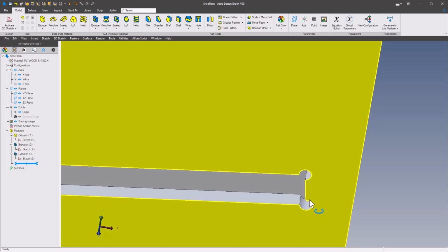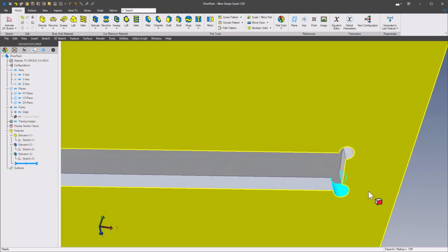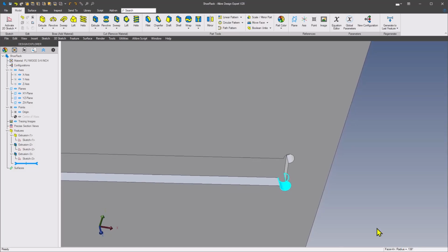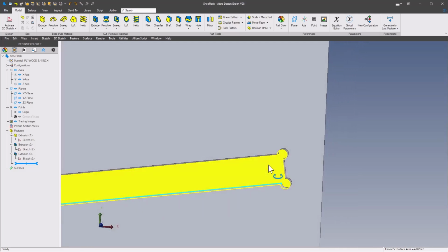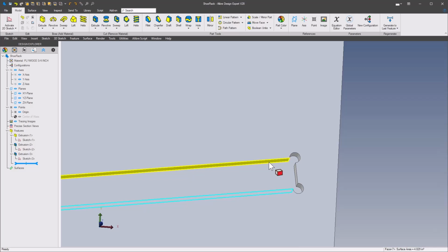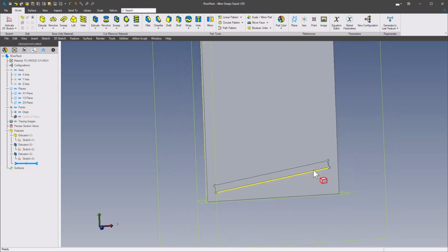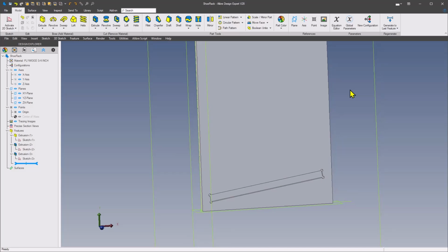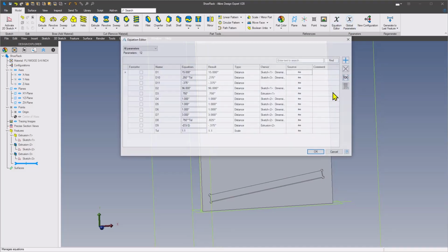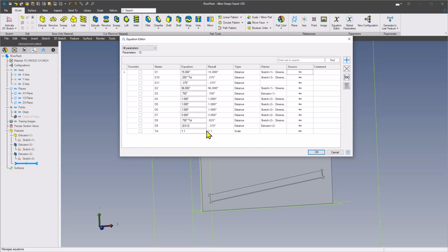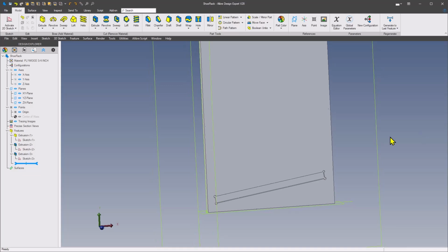So there. Now we have a larger radius, from 0.125 it went up to 0.138, and our distance across our slot is now 0.825 instead of 3/4. So that now is resized, or applied our tolerance to the slot and the dog bones. And if you need to make a change in that tolerance, all you need to do is come in here and edit the tolerance value here, and it's automatically applied wherever that's added to the other dimensions or parameters.